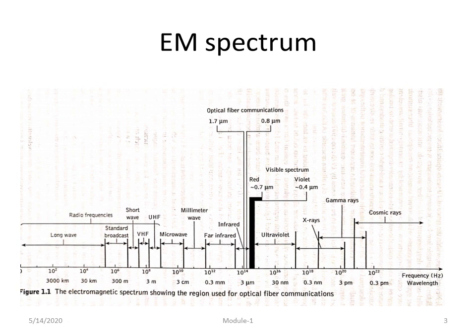You can see here the frequency is very high compared to all other communication systems. Radio frequency is around 10 raised to 4 to 10 raised to 6 hertz. Microwave is above 10 raised to 9 or 10 raised to 10 hertz. But here it is around 10 raised to 13 to 10 raised to 16 hertz. As you increase the frequency, what will happen? The carrier frequency is high, then obviously the bandwidth utilized for the communication is very high.